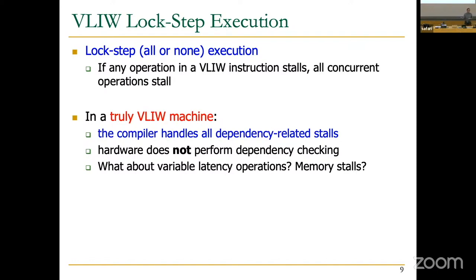So the compiler doesn't know what to do, basically. So what do you do? The compiler assumes something. If the assumption is incorrect, you stall the machine. Who stalls the machine? It's not the compiler. It's the hardware, because the hardware knows where the load is, where the data is, or where the data isn't, initially, of course, right? So that's basically why this dream is a dream. This pure VLIW is almost impossible to build in real hardware. You have to have some stall signal saying, oh, this operation is taking longer than expected, so stall the entire bundle, stall the pipeline. Does that make sense?